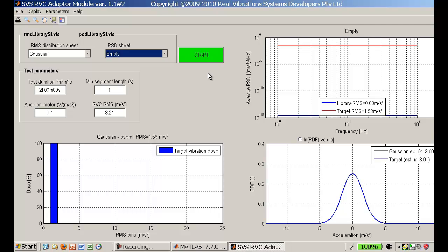Access to field vibration data is not always available. In such cases, the only option currently available is the use of generic PSD functions to generate steady-state, constant RMS random vibrations. This approach does not produce realistic vibrations, and it has been shown to have significant shortcomings.